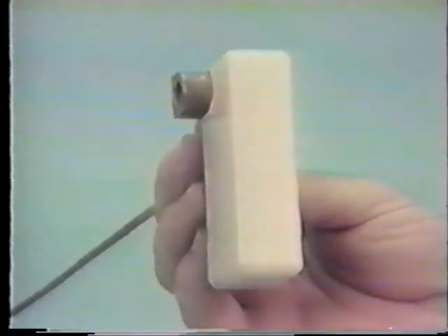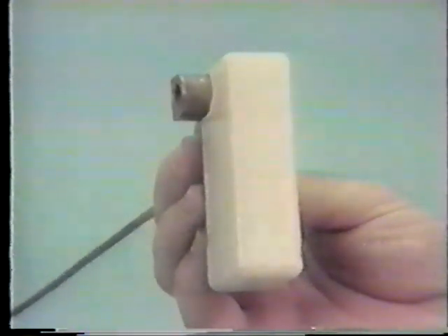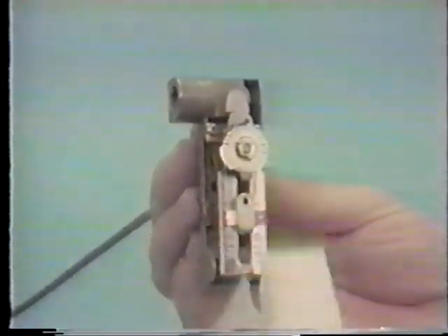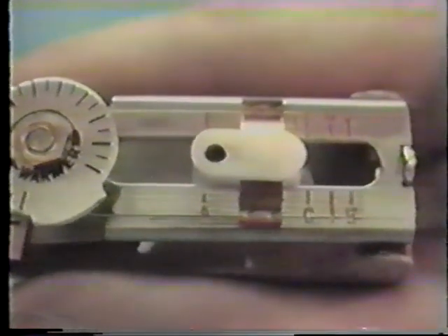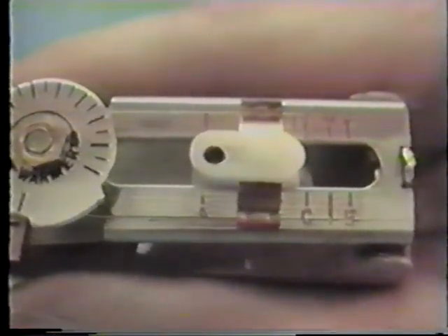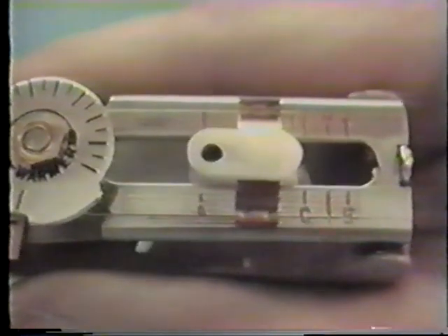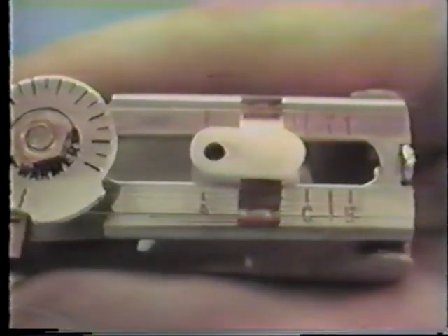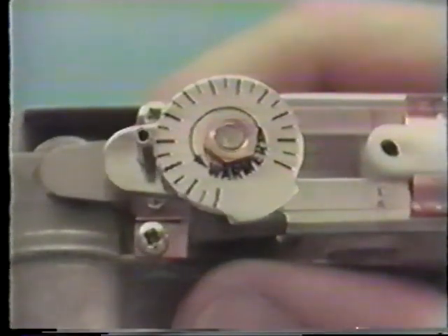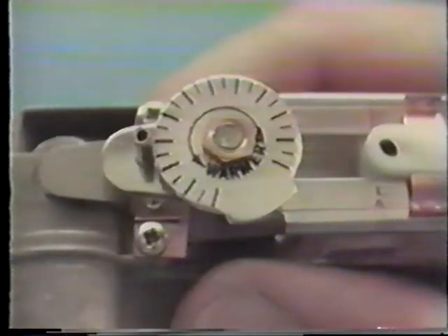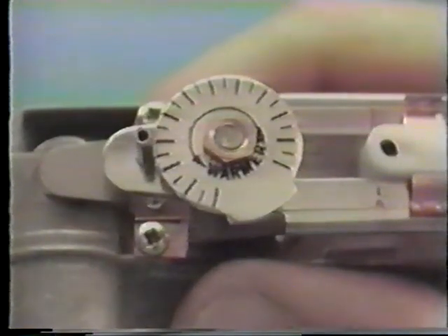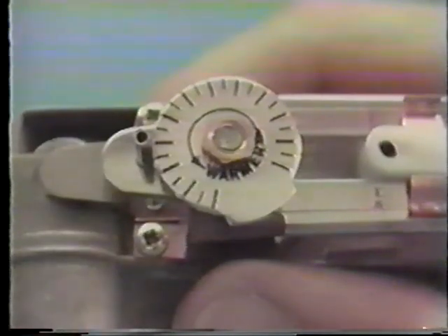The 2260 controller is shipped with factory settings of 20 degrees Fahrenheit throttling range and 60 degree Fahrenheit set point. Field adjustments are easily made by removing the snap-on cover. The throttling range is adjustable from 10 to 50 degrees Fahrenheit by means of the slide adjustment. Each graduation represents 10 degrees Fahrenheit. The set point adjustment is made on the graduated dial with each graduation equaling 5 degrees Fahrenheit. The temperature range of the device is 40 to 150 degrees Fahrenheit.